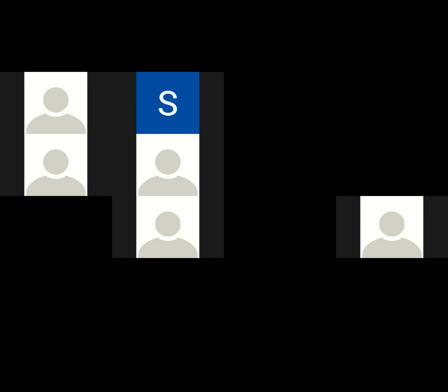Well, I was going to basically try to come at it from a different angle, Dan. I know what you're asking, because there are some MPPTs where the hookup sequence is generally to hook up the load first, and in this case, it would be batteries, and then hook up the array.